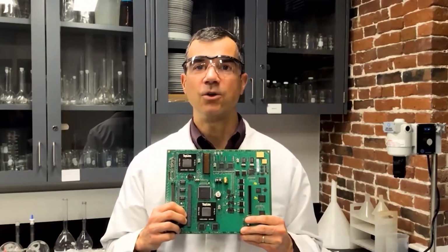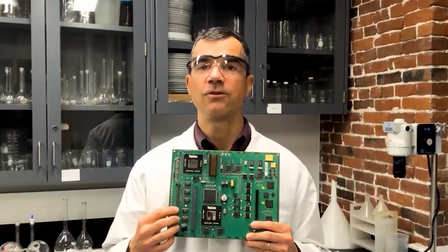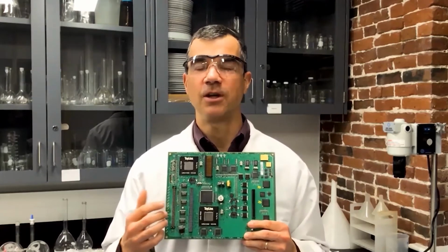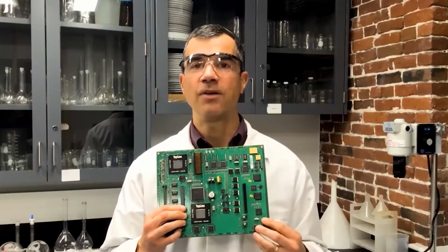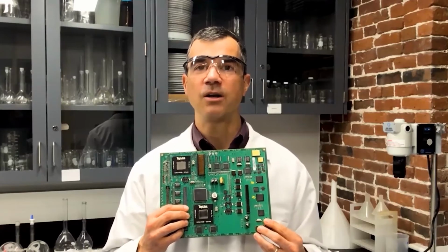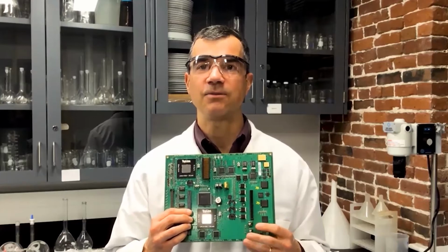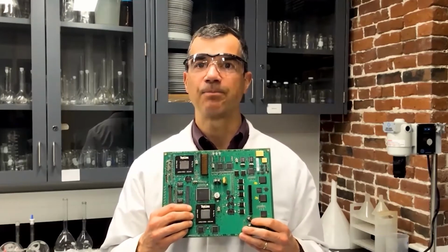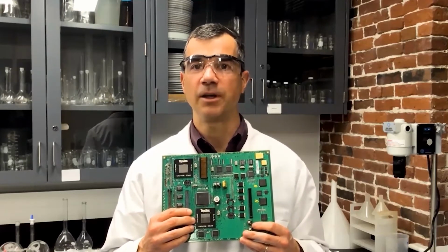We tried to have this single test vehicle encompass through-hole components as well as surface mount components, and many different types of geometry. You can see there are connectors here, there are ball grid arrays, there is just a wide variety of different types of components, both large and small, so you have different thermal masses. So this is an example of putting together a test vehicle with a number of different varieties of applications that you'll see out in the field and accomplish it with one test plan.